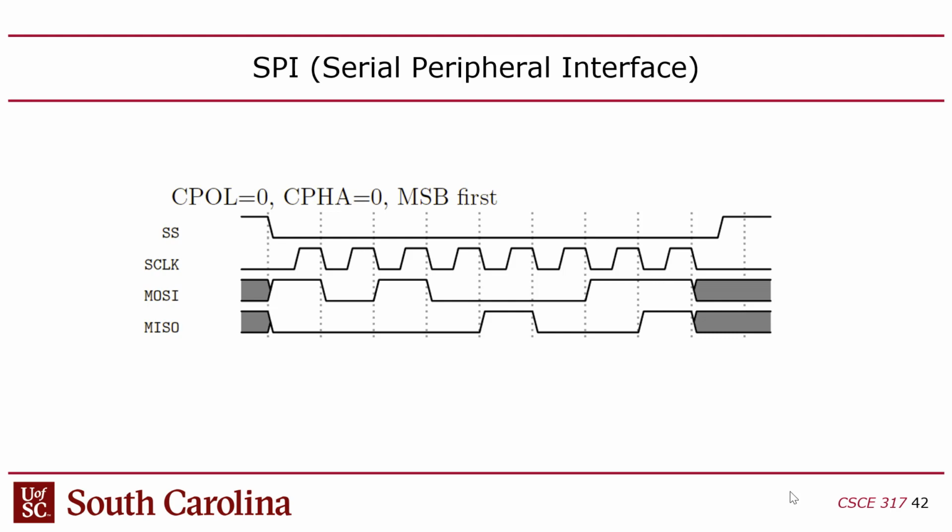Now you might say, well, wait a second, why half a clock cycle then? Why not give it more than half a clock cycle? Well, if you do that, then you start to intrude on the next bit's time, right? So if you read the data at an offset of a half clock cycle, which would be basically the opposite edge, in this case, if I'm reading on the rising edge, then I want to change the data when the clock is on the falling edge. This maximizes the time that the data has stabilized in the channel before I read it.